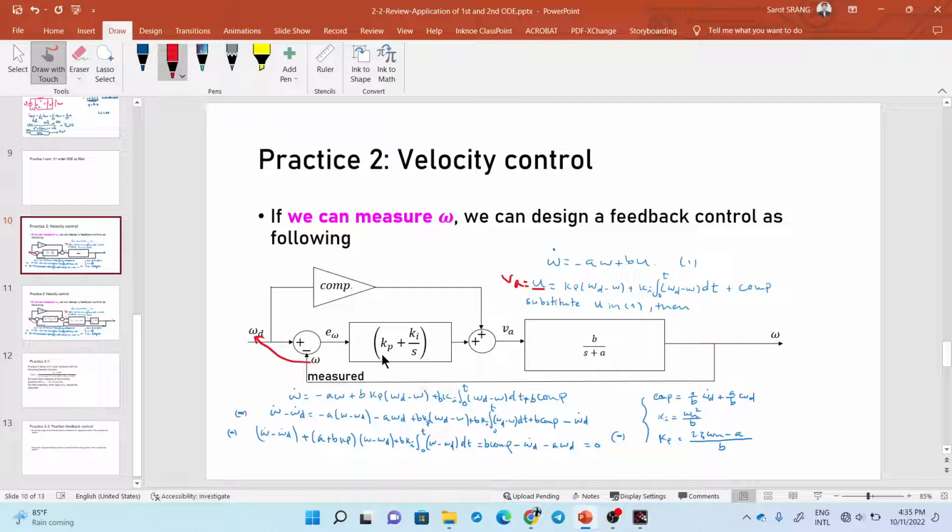And then you use a PI controller here to calculate which amount of voltage should be supplied to the motor. Then finally you will get omega actual become the same as the desired, or we can say that the error tends to 0. This is what we want. Then we need to find a way to choose the right coefficients of the PI controller, Kp and Ki, right?